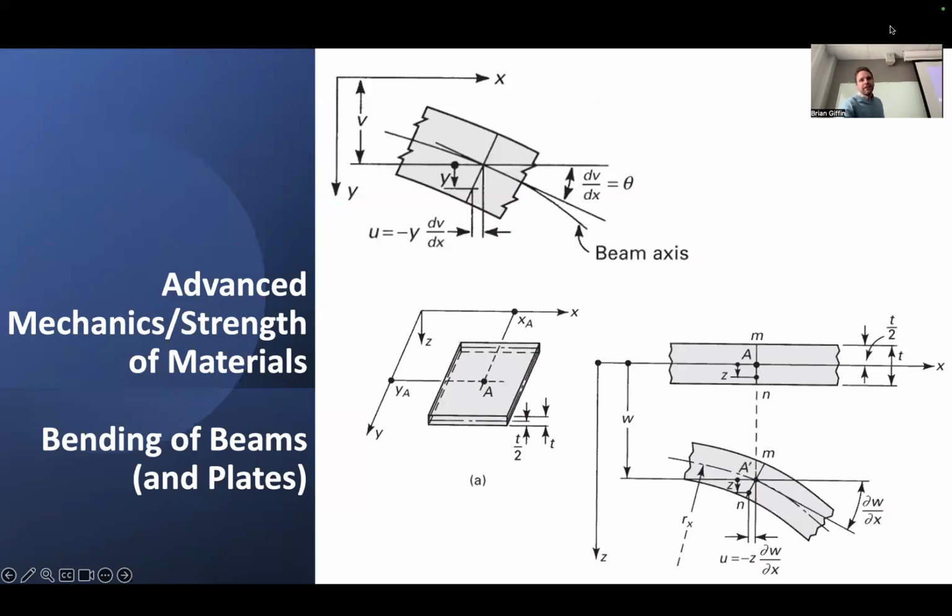All right. So as mentioned last time, when we were talking about finite element methods and some of the different element types that are available to you, I talked about really three different categories broadly of elements that might exist in some finite element code. There's certainly solid elements. Those are three-dimensional volume-filling elements like tetrahedra and hexahedra, and they're intended to discretize some three-dimensional